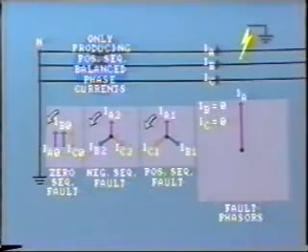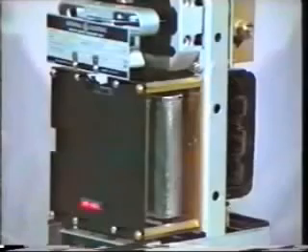So we now come to another very important conclusion, and that is where a ground fault exists, all 3 sets of symmetrical components are present. That is, positive sequence components, negative sequence components, and zero sequence components. And do note that within each set of components, the voltages and currents are of equal magnitude. The presence of these components provides a useful tool for detecting unbalanced conditions and ground faults. For protection, both zero sequence and negative sequence relays are installed.